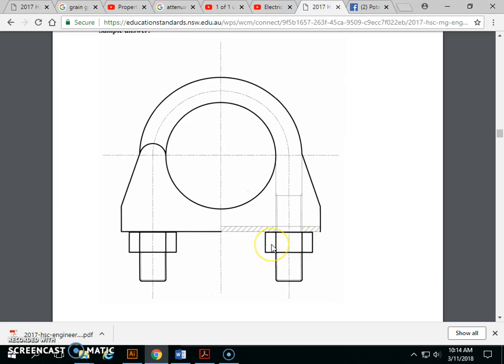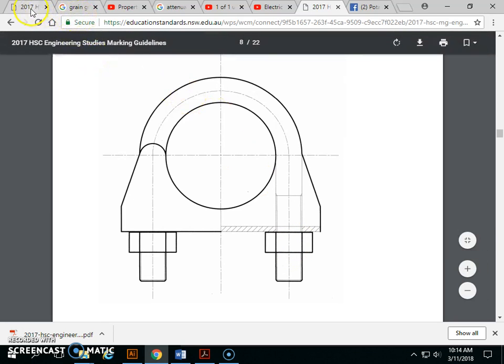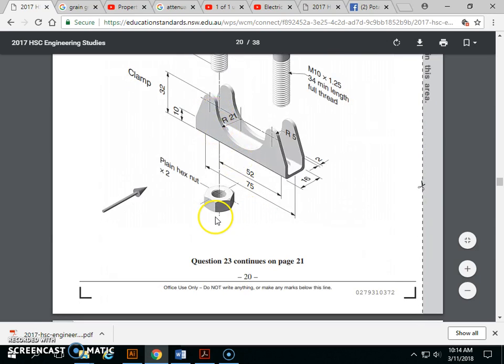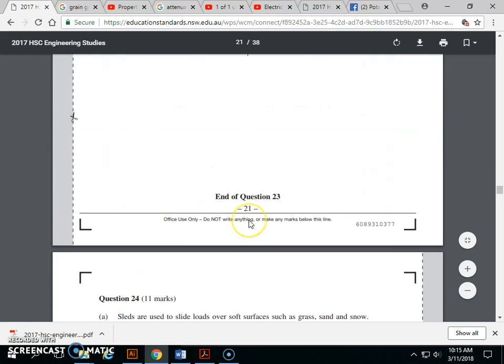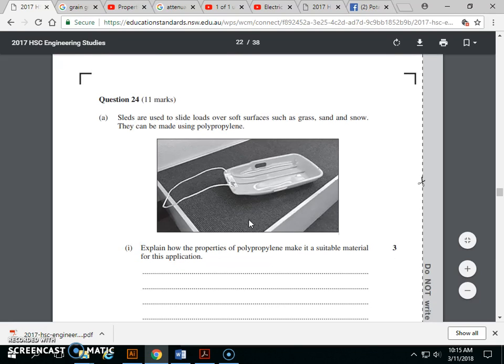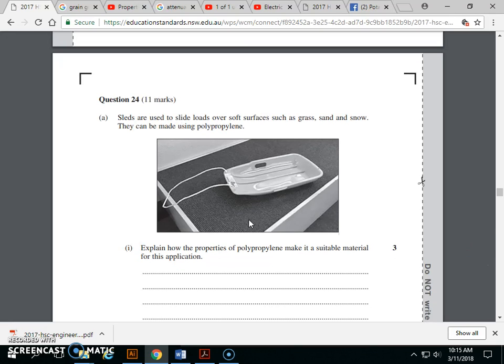The other thing, so this is not a terribly hard question. The last part that I would say you need to pay attention to is whether or not we show across the flats or across the corners. In this case, if it's across the flats, you just see one line, right? One line here. Because across the corners we see two. You're seeing three sides of the hexagon, whereas alternatively we can see one half of the hexagon. So that's important when we look at the drawing, that the hexagon, see how we can see a flat side of the hexagon. If we were looking in that direction, we would just see one line, exactly in half. But it would be a different width, which would be 1.6 times the diameter, not 1.8 times the diameter.